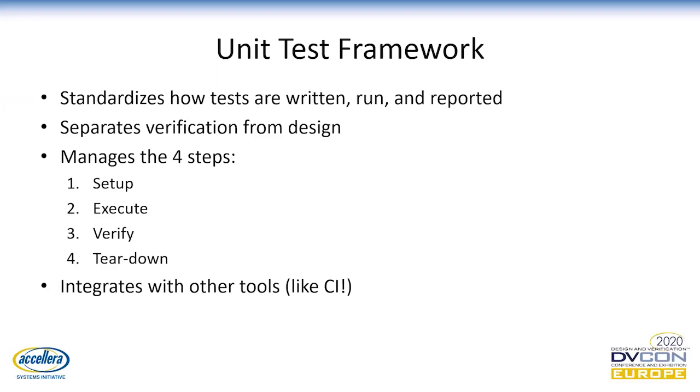So in case of MATLAB, this framework standardizes how tests are written, run, and reported. And it forces to separate verification from design. And it basically manages the 4 basic verification steps, which are setup to initialize the code or the system, the actual execution, the verification of results from execution, and the teardown phase, which is basically the opposite to setup.